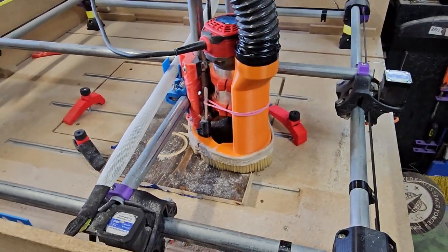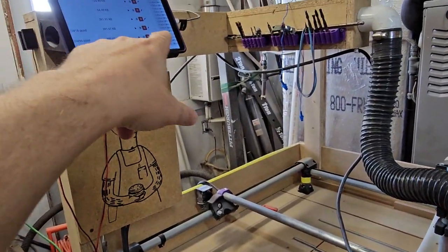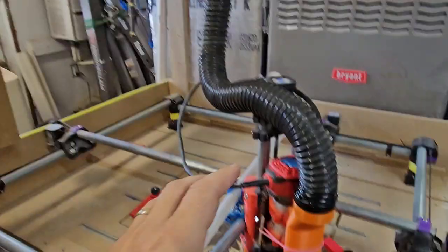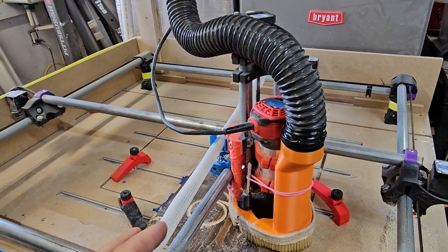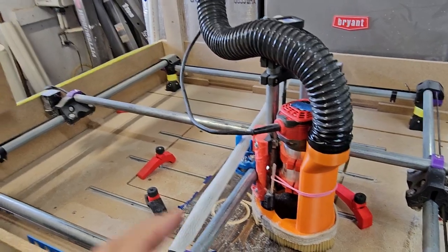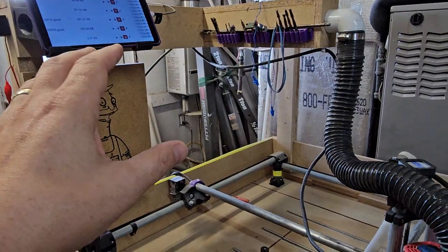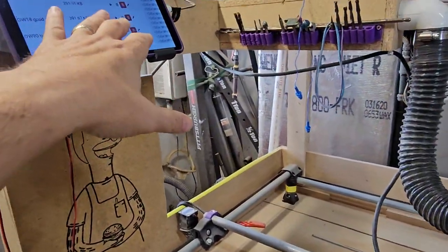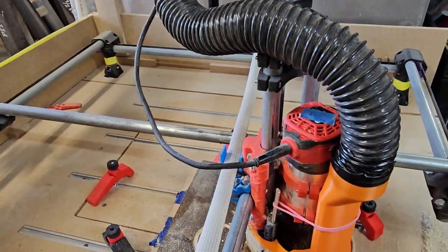We can track the G-code, we can flip to a couple different screens, but I can also disconnect the tablet entirely, turn it off, because now the board itself is running everything. As long as I'm not seeing anything go wrong with it, it will take care of everything. If anything goes wrong and I do disconnect it, my only option is to shut down the entire machine versus being able to leave it connected. I can hit pause, I can do a couple resets, I can do stuff with that still being connected.